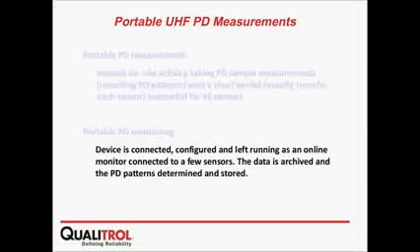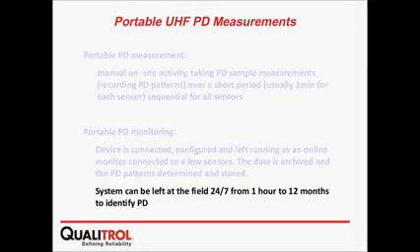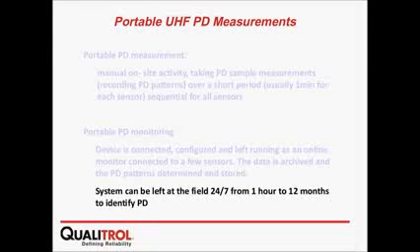That could be from a couple of hours to a couple of days to a couple of months, and that's the solution Qualitrol promotes, that our portable unit can be left a year or months, whatever the application demands. Whenever you identify that you could have a PD problem, rather than having a continuous online monitoring, you can then have the portable unit run on the asset for the desired amount of time. Some of the PD events, like the floating particles, may not be active all the time, so having continuous monitoring is one of the most effective methods to capture those events.